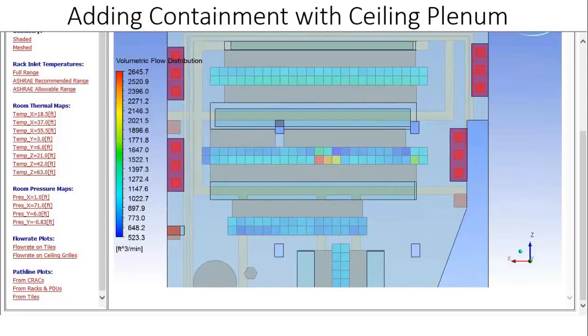I think you could probably move this up a little higher in terms of density. But this thing's behaving pretty well here. We are getting some distribution of air, so you have to be careful where your servers are. And there's an opportunity to reset here your high density perf tiles as well.